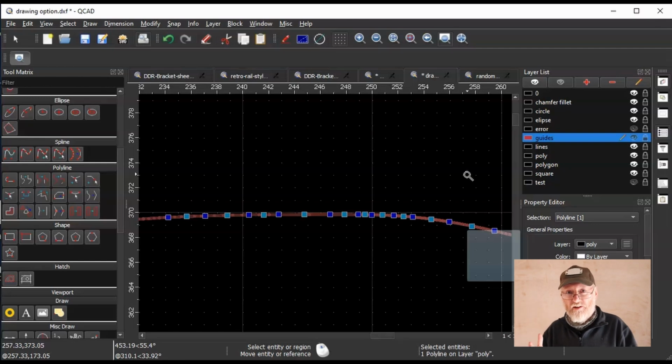Whereas if you've created this yourself, it might be perfect, chances are it's been downloaded or sent to you and needs some kind of editing or changes therein. For example, a bit you want to use may not fit in an internal curve, so you need to change the shape of that curve to make it work with your tooling. And all the way through, little problems can appear and grow in these particular polylines.